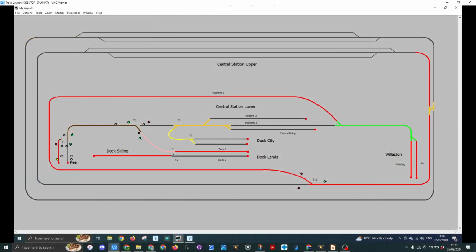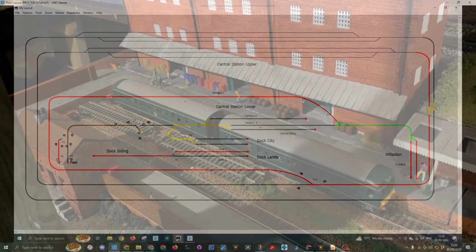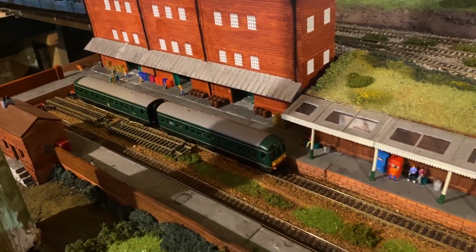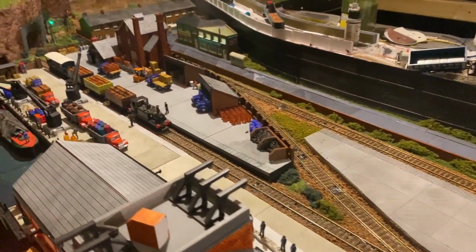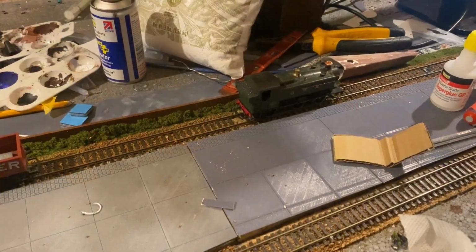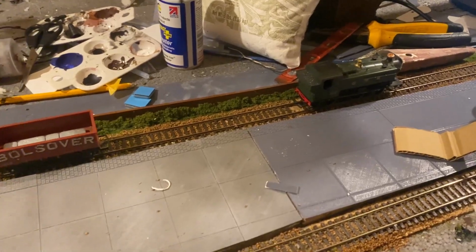So here you can see the panel view for my layout in JMRI, Panel Pro. The red sections of track tell me they are occupied block sections. These use one of the Model Electronic Railway Group DCC current detector kits, which supply the status to a single Arduino Mega using CMRI. In PL Platform 2, I have one of my diesel motor units parked up. In the dock siding, I have a Ginty with its load of barrels ready to be unloaded. And in dock Platform 1 is a pannier tank engine parked up.